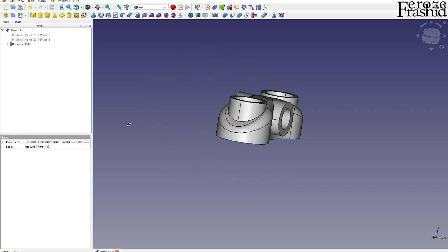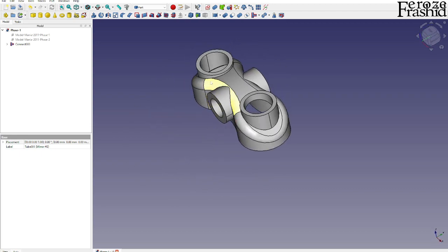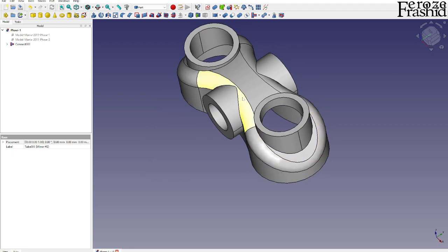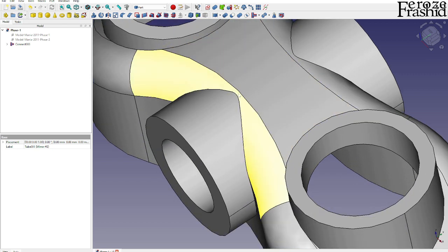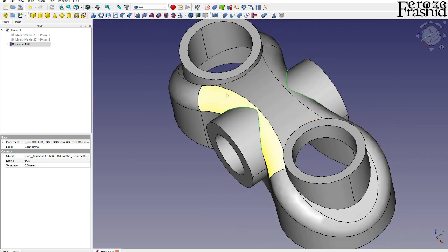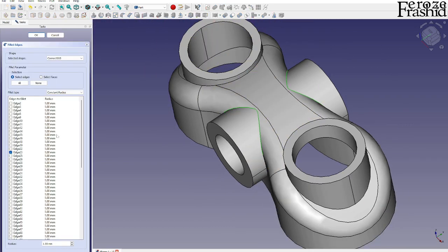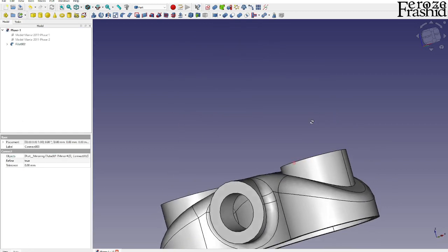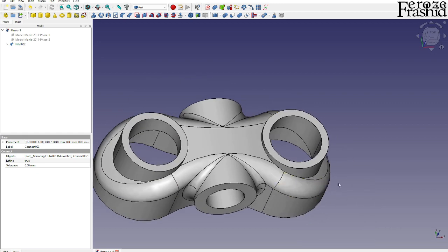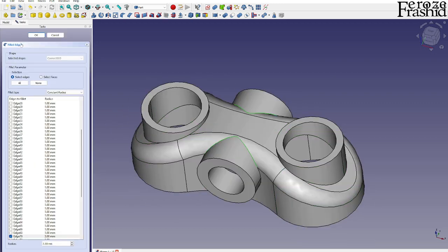All right, I think that's all other than the filleting. So I'm going to go ahead and apply the fillet right now. The main body is built. Since we did this little height adjustment in phase 1, I want to keep that, no change in there, and then go ahead and apply a 3mm fillet. Beautiful. And then we want to do another 3mm fillet on these two. So maybe we can do it from the same face.